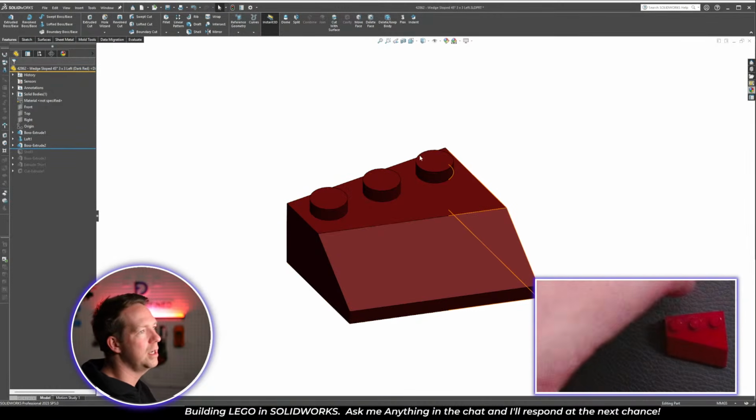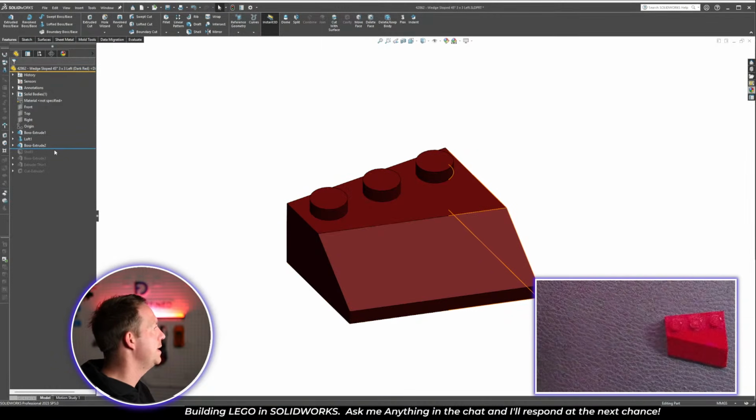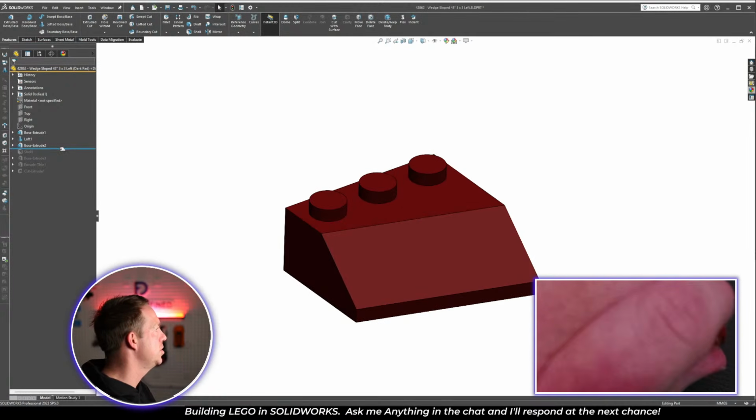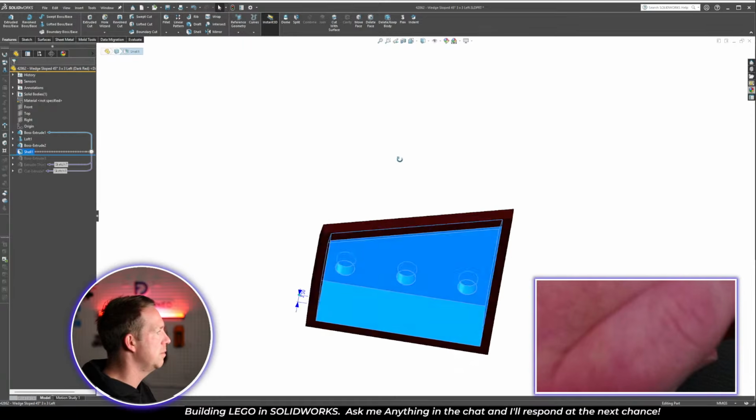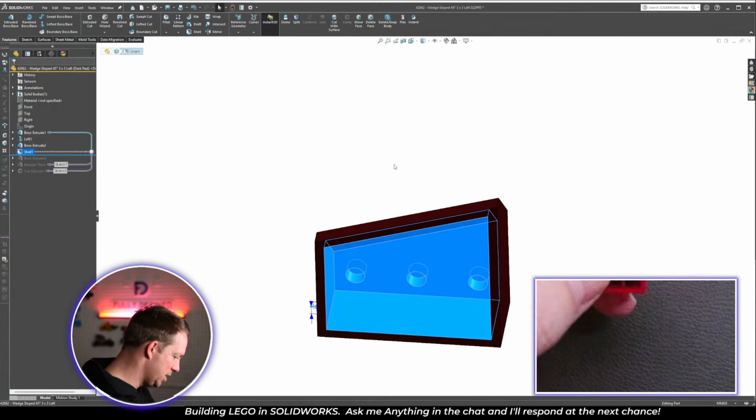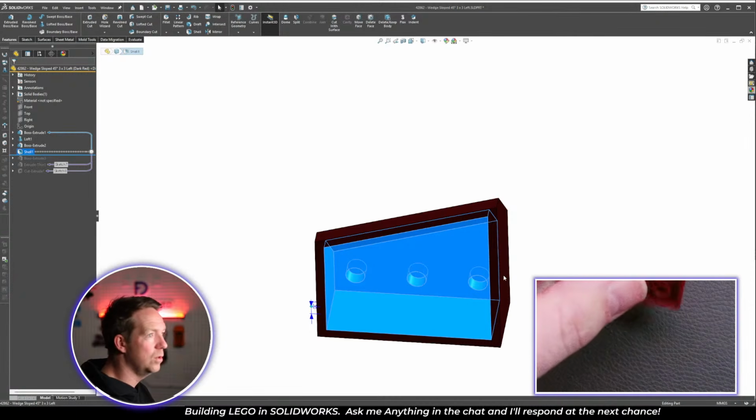As I was saying, using the feature tree, rolling it up and down means that now I can roll down on the shell feature. And because the shell was using the bottom face of the part and that hasn't changed, that feature still works without error.